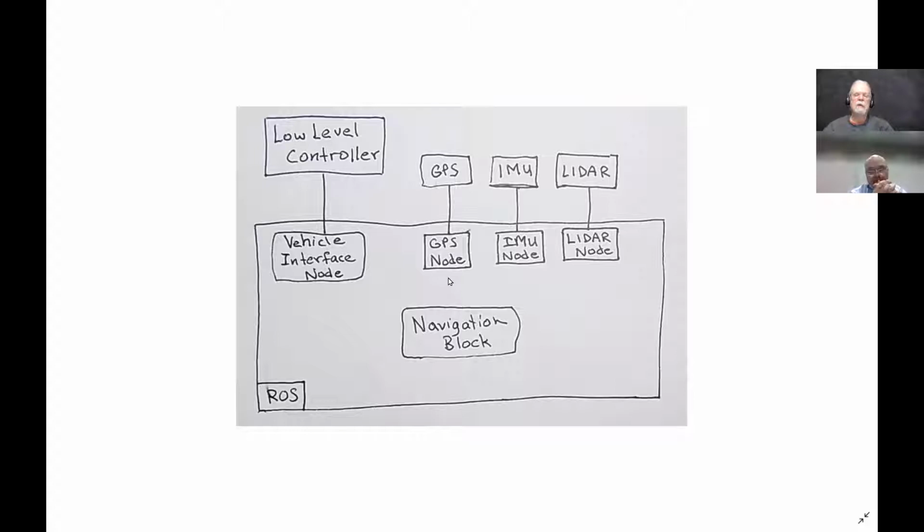So the concept is you would write a launch file that says start up all these physical devices, and then another launch file that says start up whatever your actual code is to make your robot run. And you could then combine that into one main or master launch file. So you say go, and it would execute the launch file to start all the physical stuff, start the launch file to start all the navigation and any other ROS things you've written, and the thing should come up and run. Then you can drive your vehicle however you want to do it.